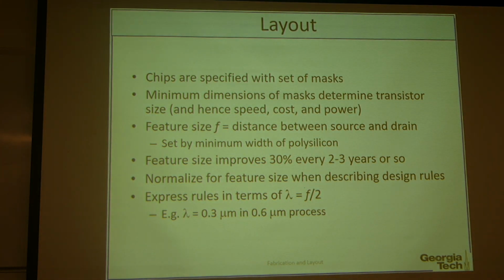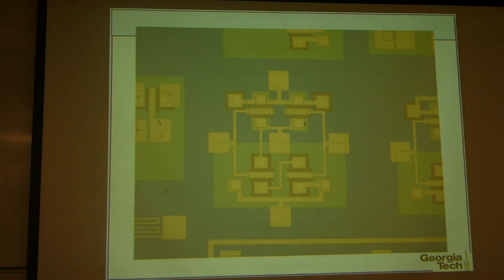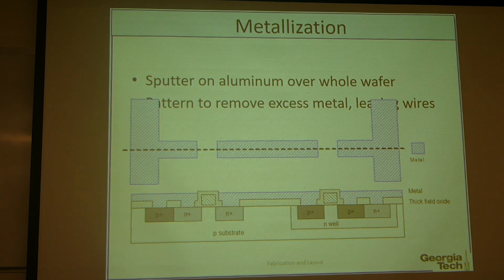Can you also explain why you said there needs to be a P plus and N plus heavily doped area? Actually, if a low resistive semiconductor is connected with the metal, it'll make a Schottky junction, which means it needs some voltage to turn it on, but we want it to be ohmic, like just a metal.